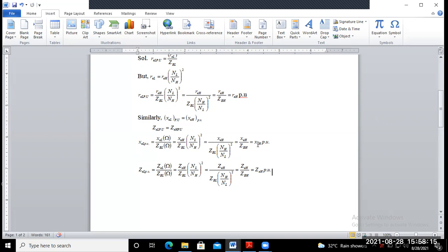You take the highest value of any component in your system as the base value or base MVA, whether it is a transmission line, transformer, or alternator.